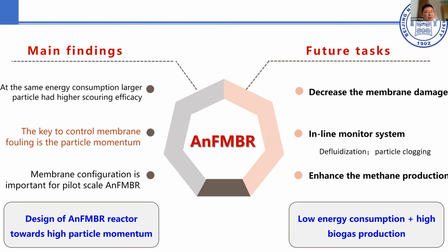Okay, finally, a short summary. The results I introduced are the main findings. One is that at the same energy consumption, larger particles had higher scouring efficacy. The second is the mechanism. The key to controlling the membrane folding is the particle momentum for the particle fluidization technology. And also for the pilot scale, we found that the particle fluidization situation is not good. So the membrane configuration is still important for the pilot scale reactor.